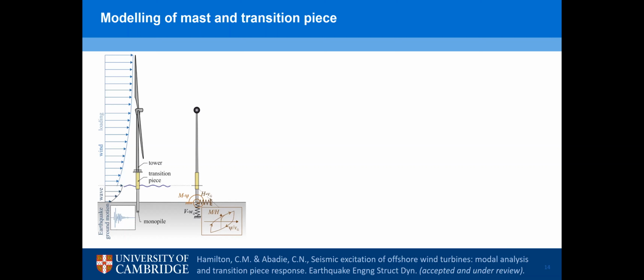then to go with a very dummy, simple model for the soil with just springs, but springs that represent the hysteresis. And we don't have anything on liquefaction here just because at the time we hadn't done any tests on the centrifuge to give us an idea of how that could be captured properly. So let's start with that.